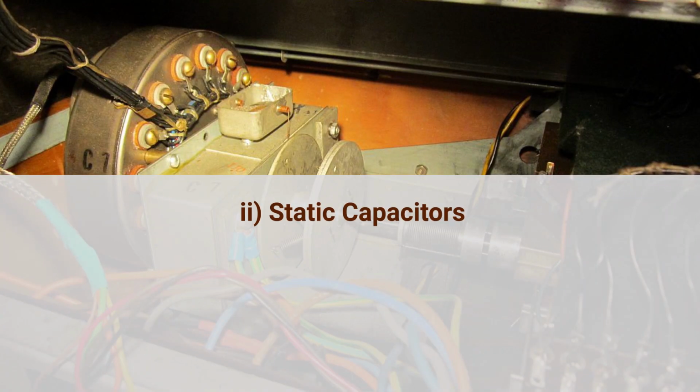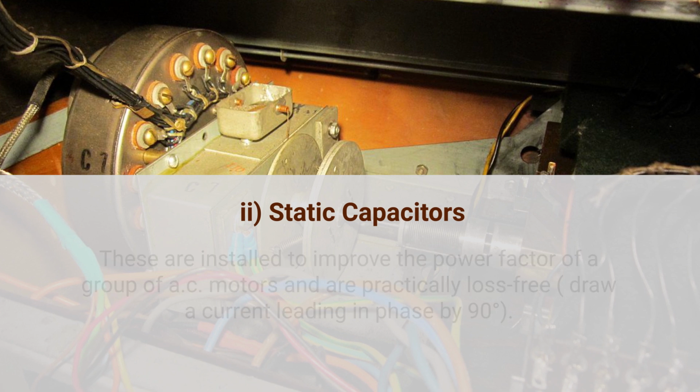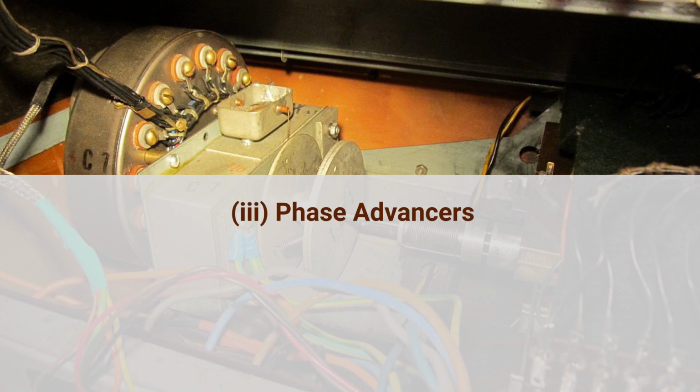The second method by which you can improve the power factor is static capacitors. So what are these static capacitors? They are installed to improve the power factor of a group of AC motors and are practically loss free. They draw a current leading in phase by 90 degrees. Since their capacitances are not variable, they tend to overcompensate on lighting load unless arrangements for automatic switching of the capacitor bank are made. The next method is the phase advancer, by which you can improve the power factor.